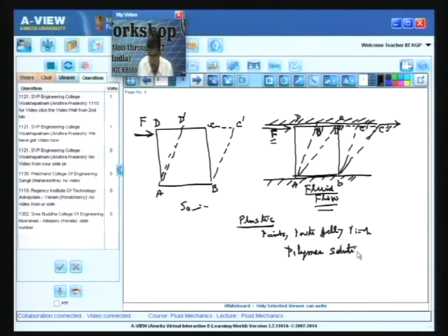So, therefore, we see that a solid resists the external stress under the shear stress. For example, here we have shown under static equilibrium condition and relaxes to the preferred shape when this is withdrawn, whereas the fluid goes on continuous deformation under the action of shear stress, however small it may be, and cannot relax back or come back to a preferred shape. So, these are the two main differences.